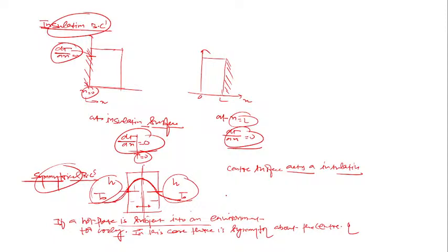And if this is the case, then the center of the surface, you can see here at the center, dT/dx will be 0. You can see here the profile. Since there is a mirror image, that will lead to the maxima at the center. And the maxima at the center means at the center of the surface dT/dx becomes 0, because the center of the surface will act as an insulation. Is this clear?